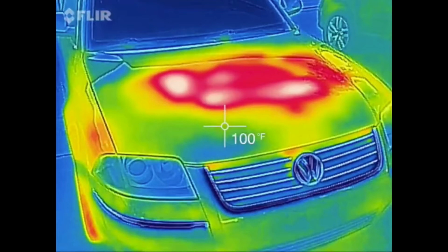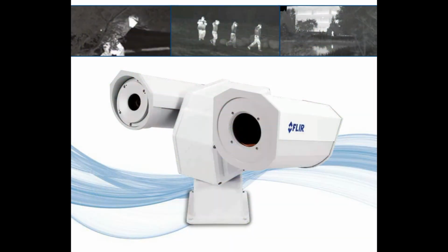If there is a reference heat source in the field of view, with a known temperature of radiation, it is possible to calibrate such temperature so that the object that you see can give you a relatively accurate representation of its temperature. Of course, like with visible spectrum cameras, the size of the pixels, quality of the optics, and the processing electronics will define the precision of such measured temperatures.